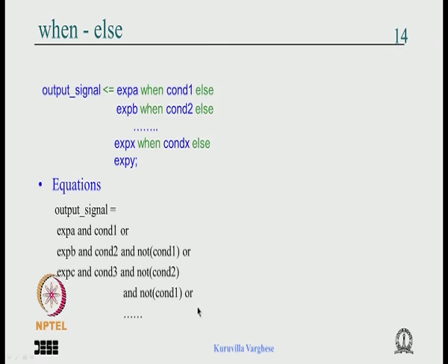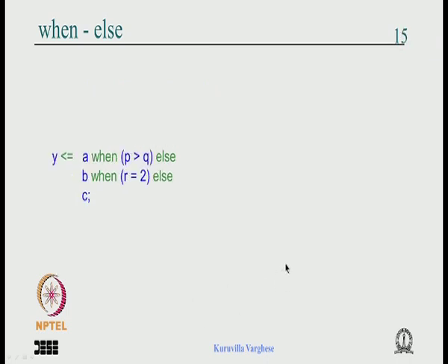And if you remember your basic course, you would have seen a priority encoder. You will see there is an AND gate. As it goes down from higher priority to lower priority, there is an AND gate with a lot of bubbles becoming bigger and bigger. So a similar thing is happening here, but there normally it is the single bits going to the AND gate, the not of the previous inputs and so on. So that's the same thing. So it's quite powerful.